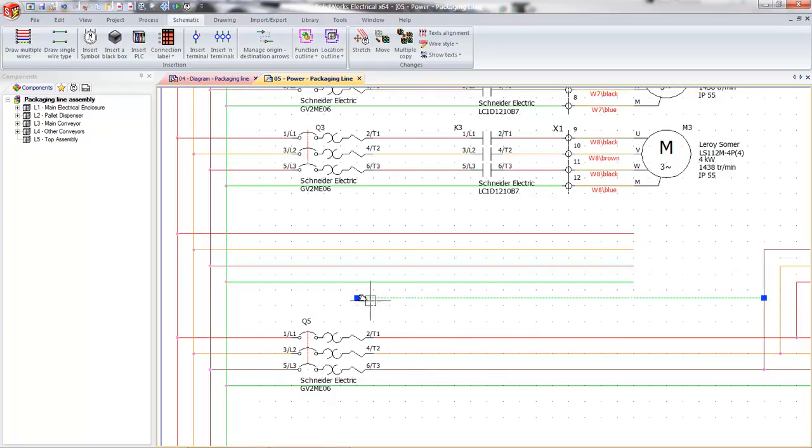Let's say I bring this endpoint here along this line here, and it does the same thing. If I bring it back somewhere on the other one here, it disappears, and it fixed this line. So it's really a dedicated tool to create valid wires. I don't have to deal with a trim function and delete or fillet zeros and so on.